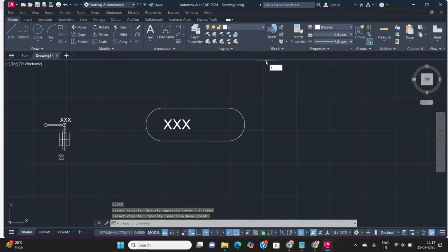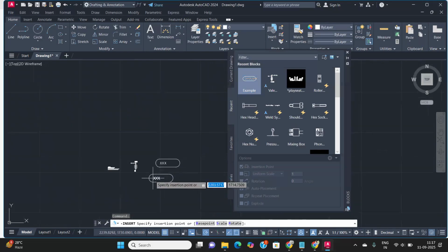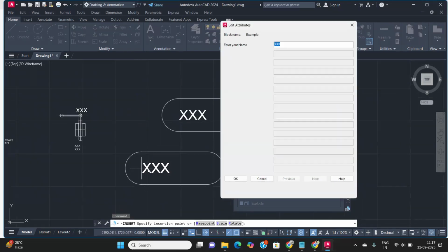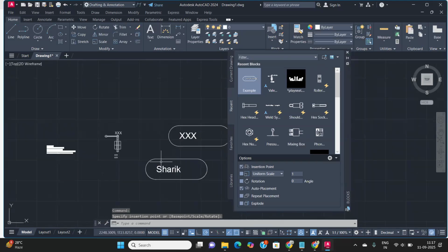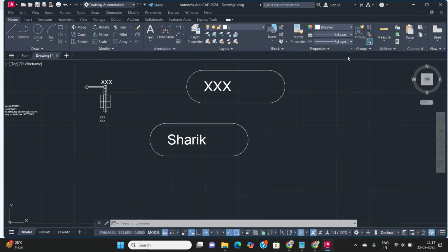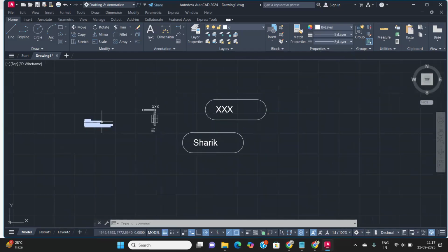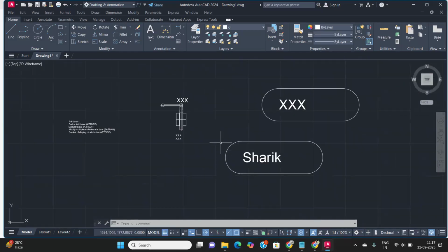If you insert the block and then those I create here, if you create here, just click on this part and then space for where you want to show it. Just click on it. And then here you can write any name, okay? Name whatever you want here, okay? So suppose I name it, sorry, okay? And then click here is okay. Then this name will appear, okay? This will be used for defining your extra feature inside your block. This is called the attributes, okay? And attributes work with the blocks, not the other way, right? By this way, you can define the attributes.